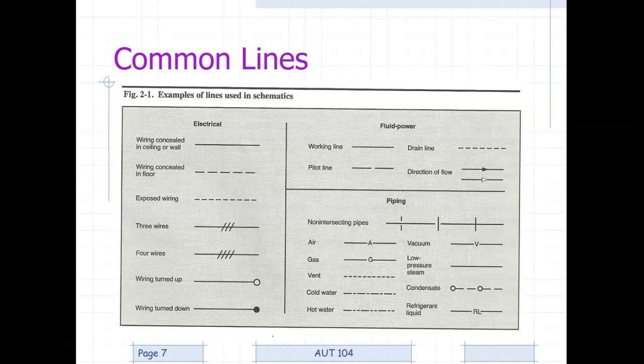All right, so you have ways to show direction of flow. Those of you that have been in my hydraulic pneumatic class, what does a colored in arrow mean? That is a hydraulic line. If it's clear like that, very good. It is pneumatic. And then you have the pilot line, which all that really means is that you're using either the air or fluid already in the system to change the state of a valve. We'll get into that more when we get towards that.